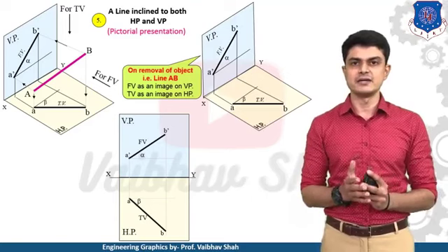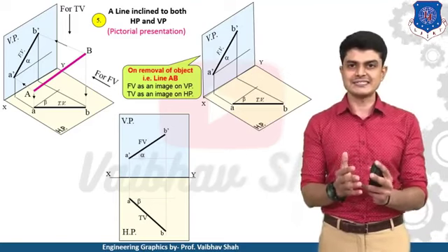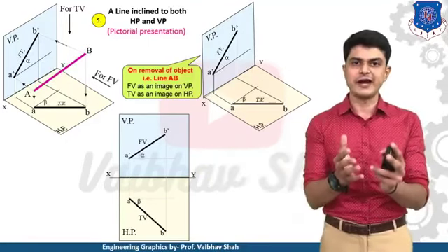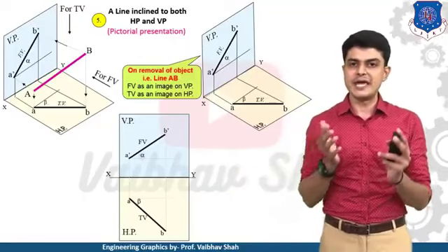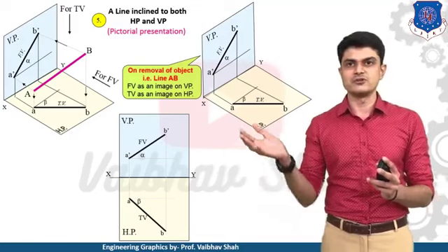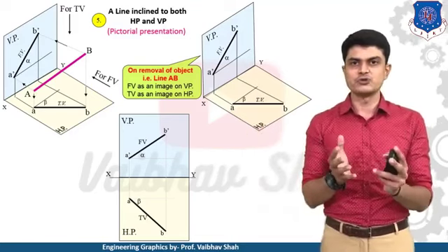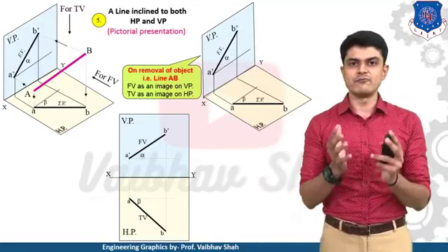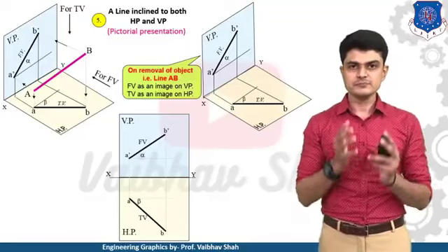In the final figure you have this XY line that you need to draw in the examination. After drawing the XY line, you first identify your point A using the projection of points chapter. Then you draw the top view line AB at angle beta, and from that line you draw a vertical line to identify point A dash. From A dash you draw the inclined line at angle alpha, giving the front view A dash B dash at angle alpha.